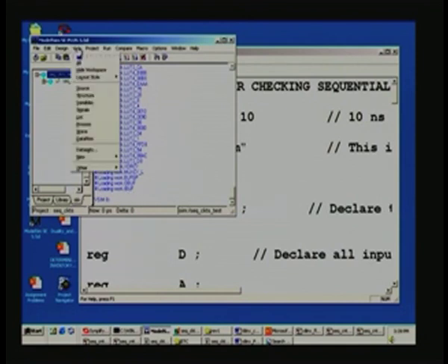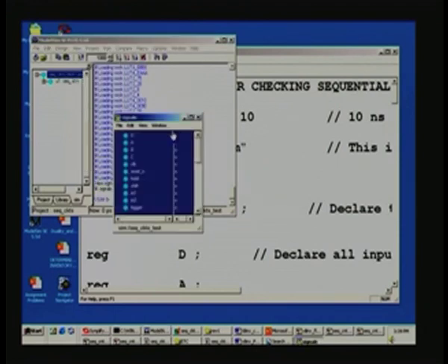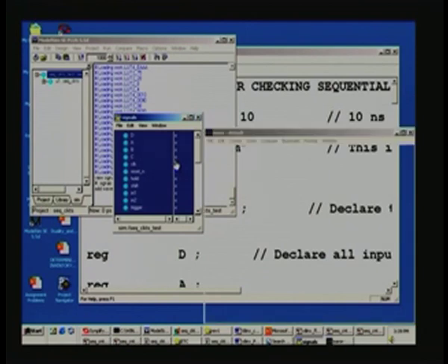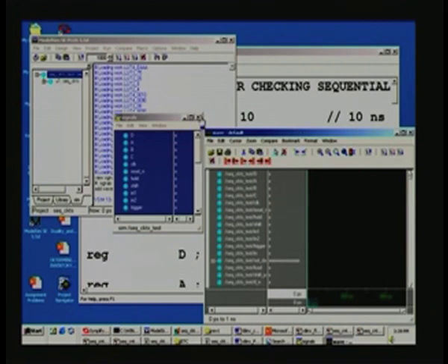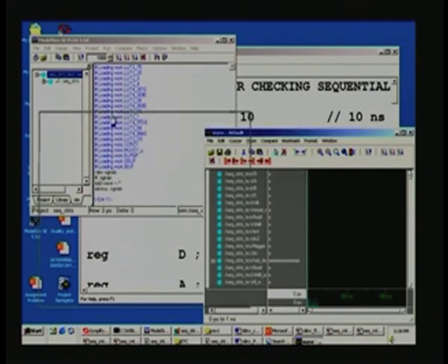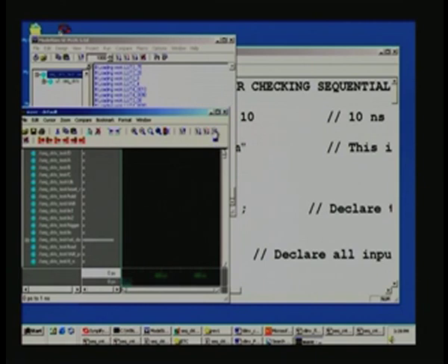In order to see that, click view, then signals, then again view, then wave, then the final last option, signals in design. So, it has opened the wave file; you do not require the signals anymore, and if you click on this it will run.